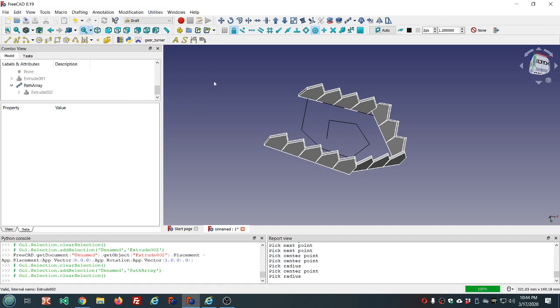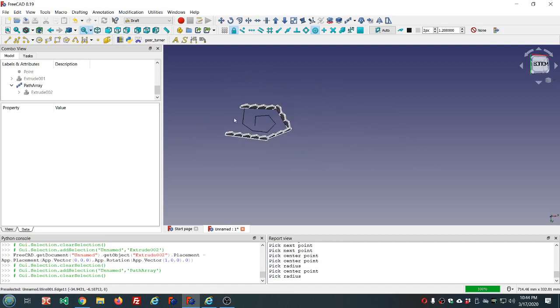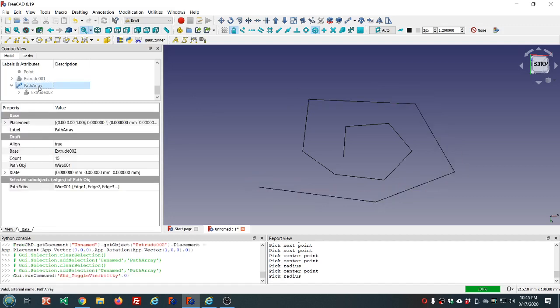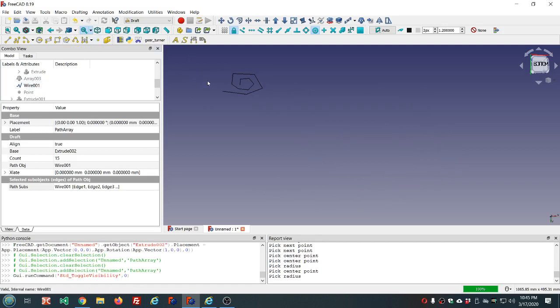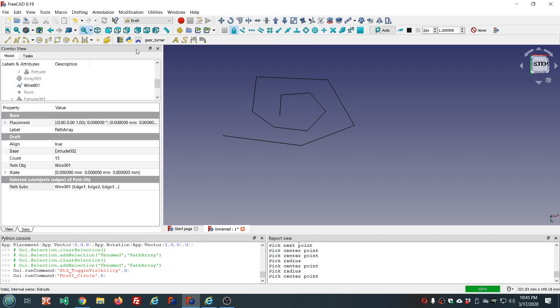So we don't have to use a sketch with points. It's a really convenient way to do it, but you could also use these points here in the inside of a compound. So let's look at doing that. Let me add also a circle because I want to show you this feature here. And cancel. Let's set my view from the top.